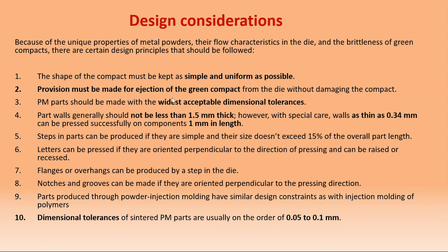And then consider what is an acceptable dimensional tolerance. And then there are some parameters for wall thickness, and steps in the part can be produced if they are simple and do not exceed 50% of the overall part length. Okay. Lettering can be pressed during the compacting.